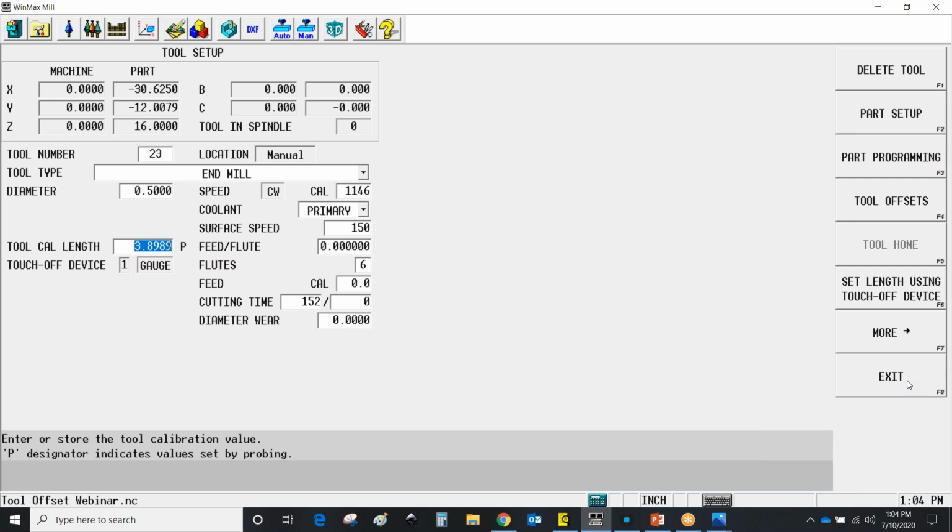There are lots of reasons, as many of you know, why we would want to leave that table active. One good example would be if I'm using, in this case, a 1/2 inch end mill, and I'm using that same tool to machine 2 different depths on some features or 2 different levels of a couple of shoulders or something, and they're very accurate or very high tolerance.